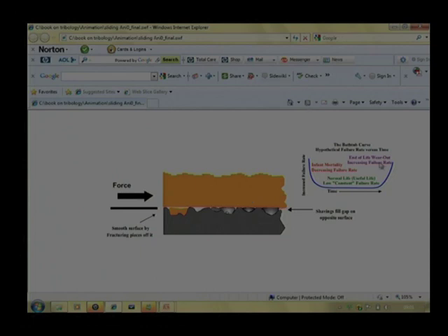That is why, when we refer to the bathtub curve, we say there is a possibility of very high initial wear rate. It slowly comes down, it reaches a steady state condition, and after a certain duration it increases. So, we say that this is infant mortality, that means in childhood the material is bound to wear out more. Then it will reach normal life, where it has to show its own function. When that functional life is over, then the wear rate will increase. This is the end of component life.